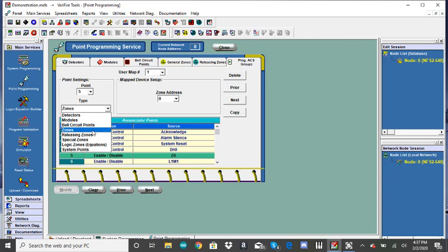You can then also program that control module so that when the carbon monoxide alarm trips, it doesn't trip the NACs and it doesn't trip the fire alarm function of the panel, but it trips that control module, and that control module in turn either trips the signal that you are trying to use to alert people that there's carbon monoxide in the building, or you can use a relay module, and that relay module can trip a carbon monoxide monitoring system.